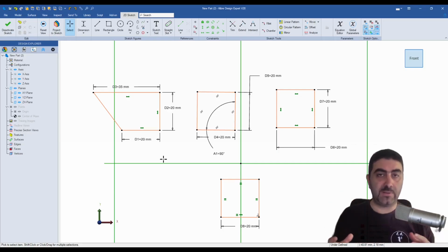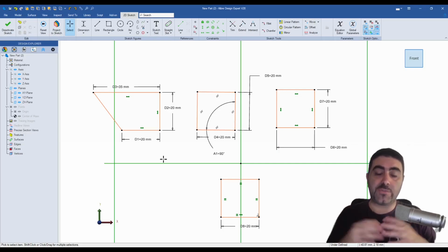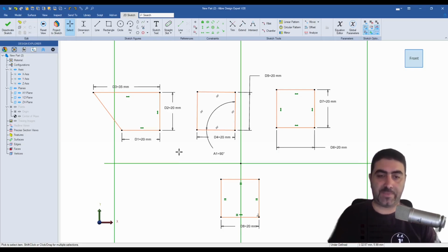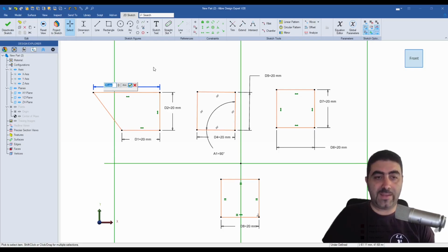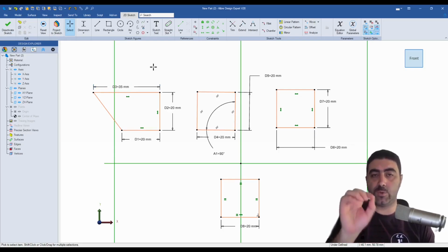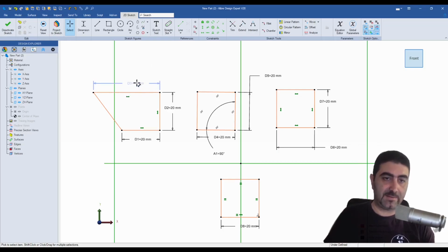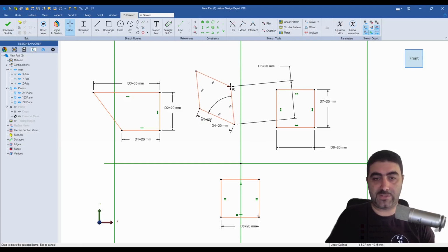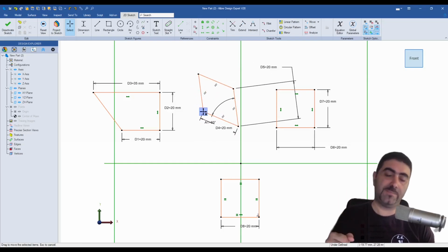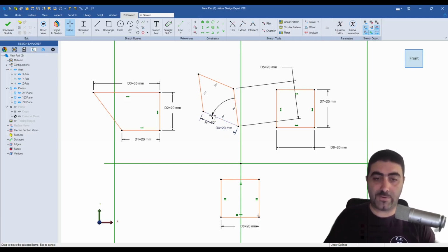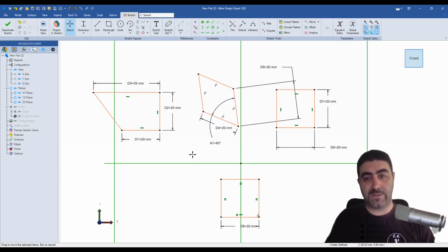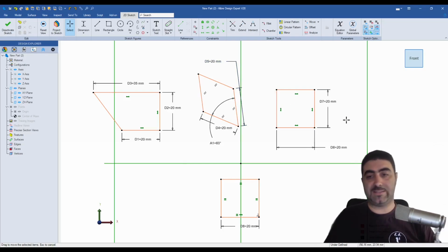So look, in this first shape here, we used our sketch elements and our constraints to define a set of shapes. And that set of shapes were the trapezoidal shapes. Fun fact, trapezoidal comes from a Greek root, and it basically means like a table. We then used our dimensions to get a square shape out of that set, right? But this shape is not inherently square. This is a trapezoid. Now, if we go here and change this to 60 degrees, well, what do I get? Well, I get a rhombic shape, right? So that wasn't a square after all either. That was a set of rhombic shapes, and we used our dimensions to get a square out of that set.